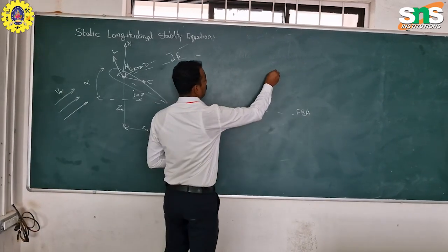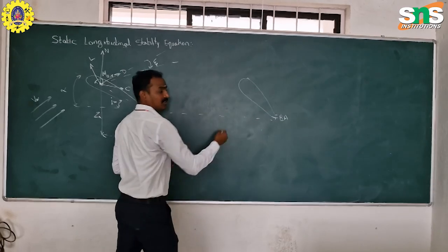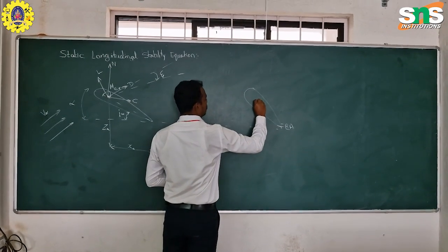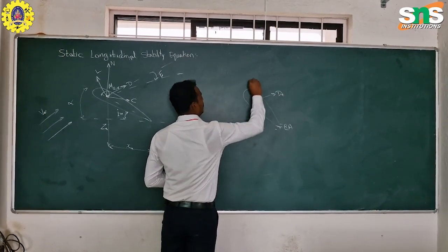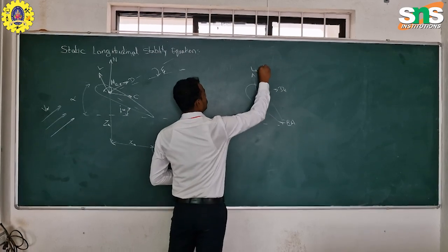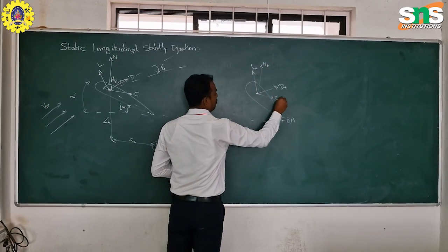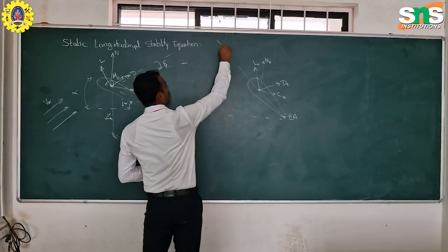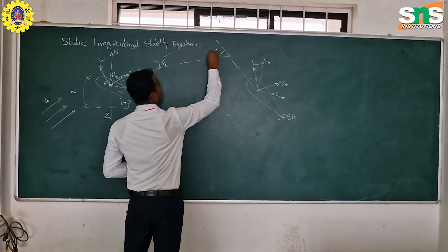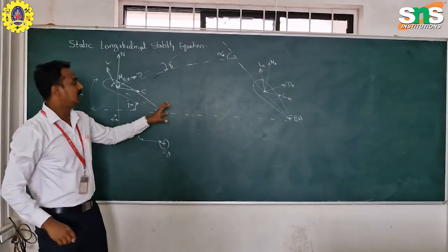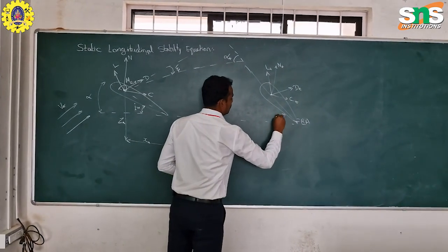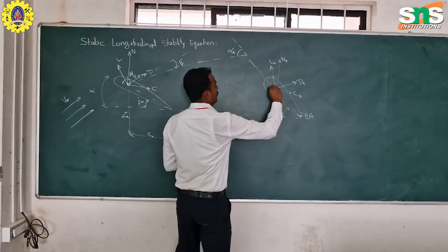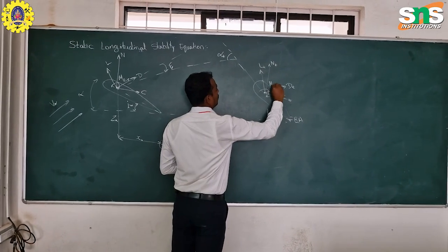Now we are going to draw the tail section. Again it has its own aerodynamic center. It will also produce drag of tail, lift of tail, normal force of tail and chordwise force of tail. We have some angle of attack, alpha of tail, which is the angle of attack of the tail. The tail also has its incidence angle i_t, and it produces some moment about the tail.